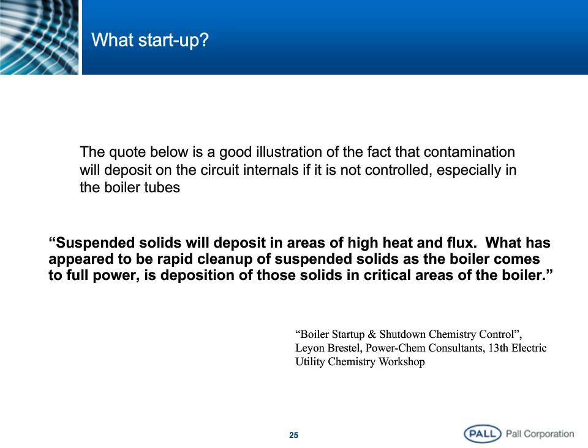And that's key. What it says is, yes, your water will be clean. Your water will get clean. But the reason it will get clean is because all the nasty things that are in the water are actually now on the side of your boiler tubes, on the side of your piping, and on the surface of your turbine blades.